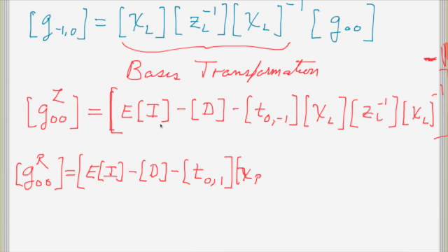This would be your right moving chi's, your right moving propagation factors. But notice they're not inverted now because you're moving to the right. For the right lead, I've got 0, 1, so I'd be looking at the response going from here to here, and that's just Z, not Z inverse.